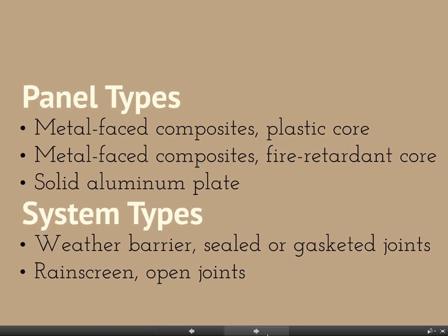Yeah, and I had a very similar experience, Vivian, and that's why I'm saying the sheet metal, even if you try to do field fabrication, you have to be really careful which direction you're installing, even if it's all coil coated, because turning the direction will make all the difference in the world. Yeah. It'll look like 2 different colors. Yeah, I always warn my architects that if they want a silver metallic job in particular, that when they say they want their mullions to match their ACM to match that field painted something or other, they should just go ahead and give that up right now.